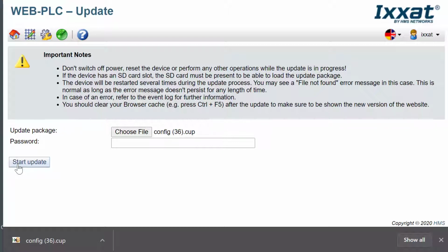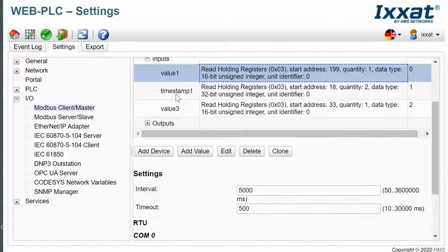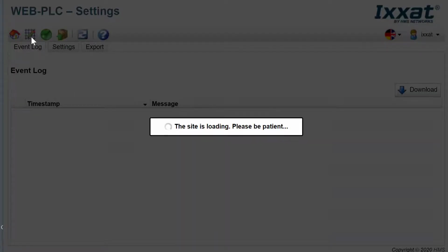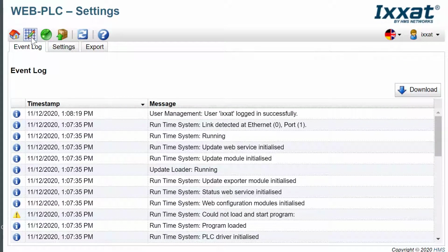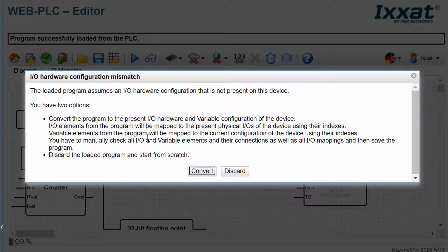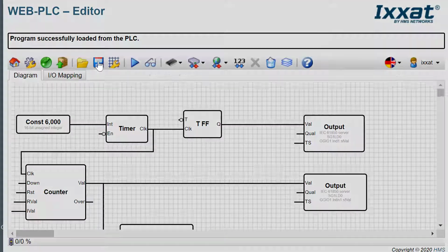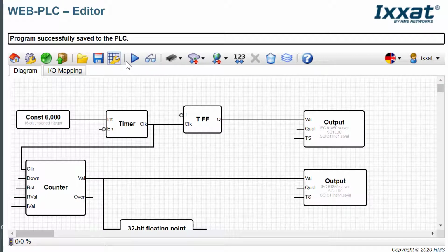Notice that the PLC might stop if you load it on a different SG gateway model, or if something changed that is used inside the PLC, for example a data point setting. Then you must open the editor for an automatic conversion of the PLC program first. Then please check if the mappings are all correct, just to make sure. If something is not converted correctly or if there is a missing part, this must be fixed. Afterwards, save it. Since the PLC stops working whenever the Save button was clicked, never forget to restart the PLC.